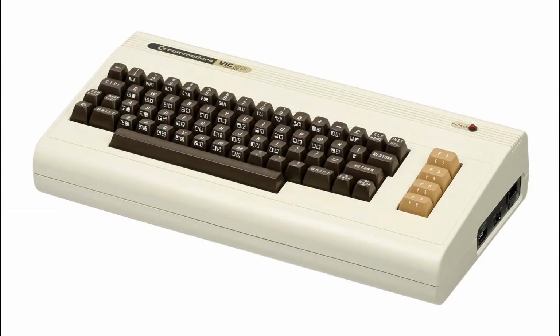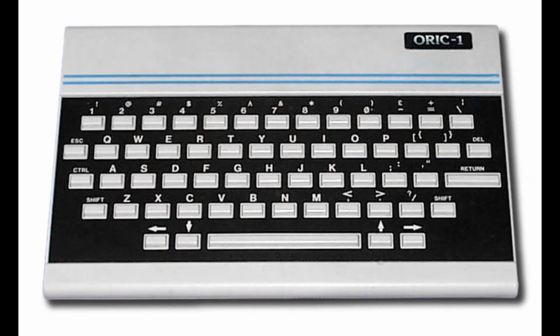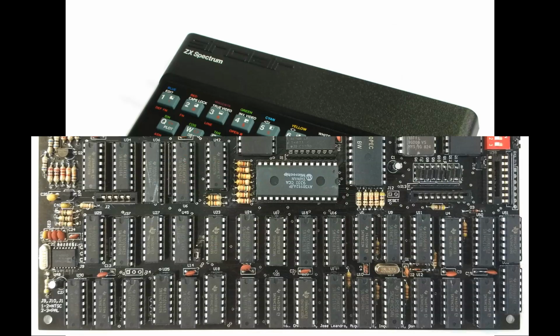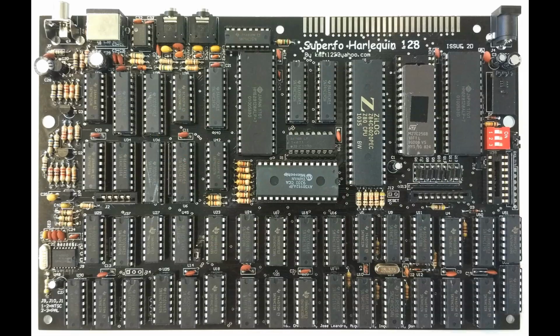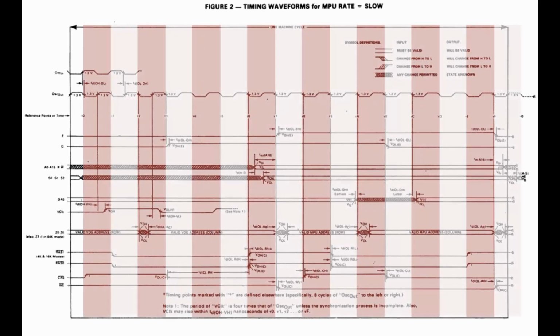In pretty much any other 80s home computer, this would have been called a ULA and served double duty as a video generator, but not here. Instead, we have a device dedicated to a small number of activities that would otherwise generate a sprawl of logic ICs. Generating the clock signals is probably the simple bit at first glance, but even that is more complex than you'd think. The master clock is divided into 16 cycles, and almost each cycle triggers something or other.